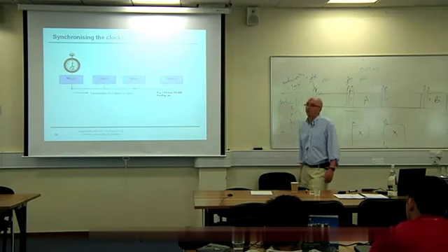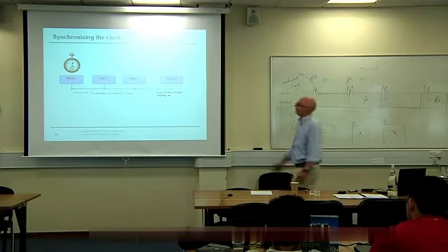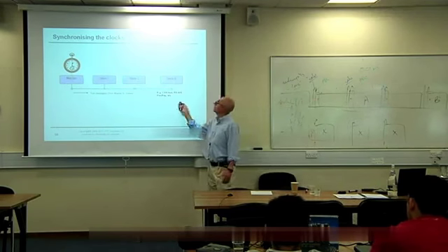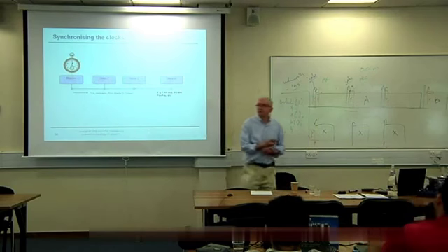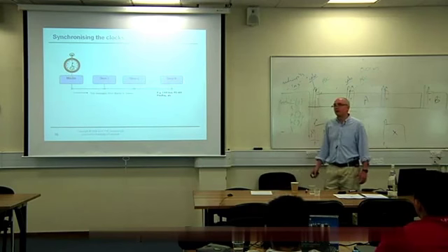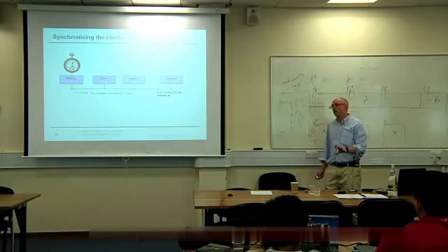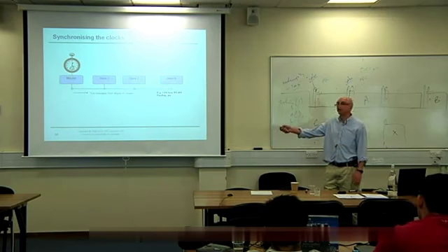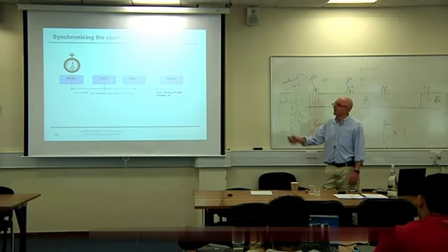And then we have two options. What we might do with this one, typically this one at the other end of the bus, is we might have this one wake up from a watchdog reset and listen to the bus. So I've woken up from a watchdog reset, that means something has gone wrong. Is there another master on the bus? Listen. Can't hear anybody. Okay, I'm now the boss. The king is dead, I'm now the king. Right, and I'm going to start sending ticks down here.